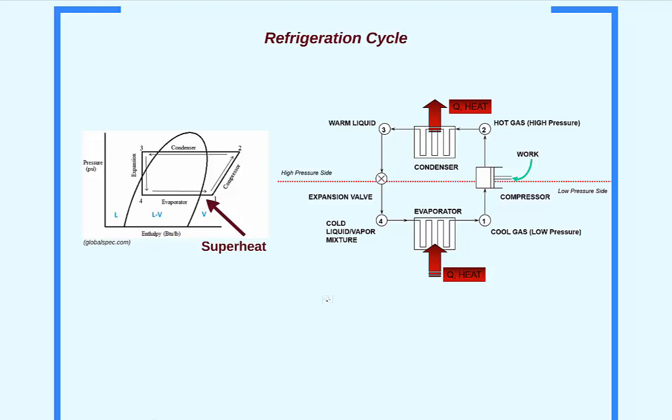In the last step, the refrigerant travels through the expansion valve, where the pressure decreases back to the evaporator's operating pressure. As the pressure decreases, so does the temperature, which allows the evaporator to pick up more heat from the indoors. The refrigerant is now a liquid-vapor mixture where it enters the evaporator and the cycle continues.